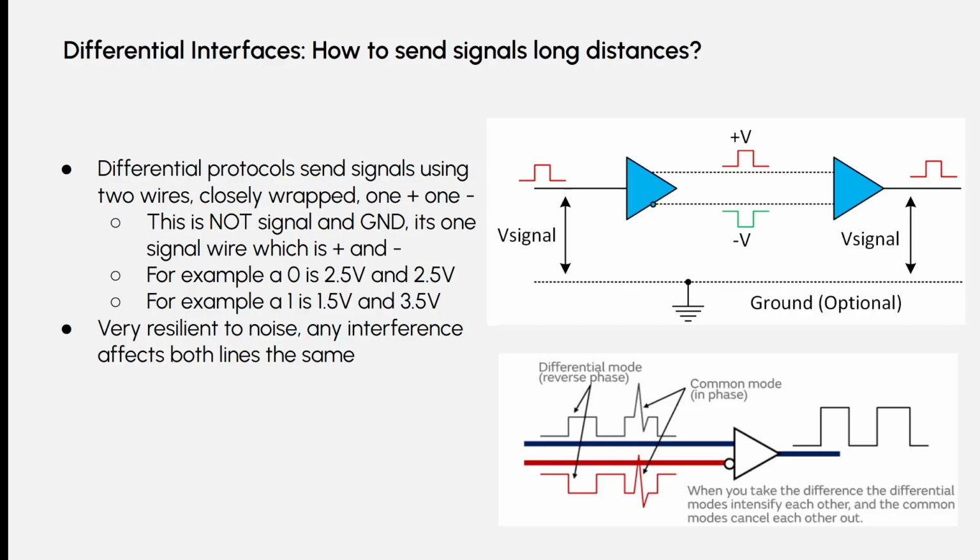So the solution to this is differential signaling. Differential signaling, I basically just look at the diagrams, but rather than just sending a ground and a 3.3 volts as a positive, you have 2 signals, and the negative one is not necessarily ground. It is just tightly coupled to the positive one, and you basically send a difference. So you pull the negative side low, pull the positive side high, and then at the output, you read the difference between those 2. It is sort of shown here.